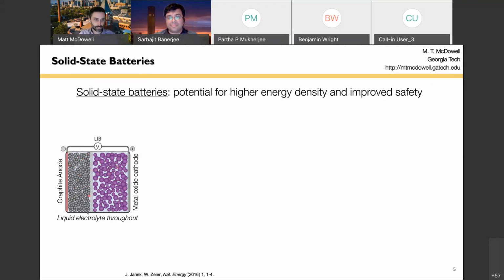There's a polymer separator in the middle as well that separates the electrodes. It's not really that important what these materials are, but what you should know is when you charge and discharge, the electrons go out to your external circuit to do work, and ions travel back and forth inside the battery. The lithium ions are inserted into the graphite and removed from the graphite, or simultaneously inserted and removed from the other material.